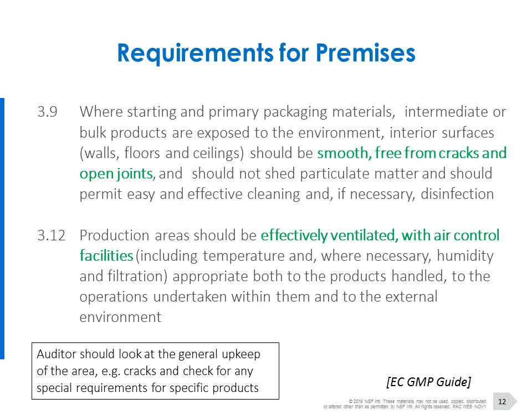So you will see, certainly where there is open product, most companies will not permit wooden pallets to be present in that area, and they typically use maybe cardboard or plastic pallets. But generally, if you're auditing the premises, you should look at the general upkeep of the area. Remember, there will typically be many forklift trucks operating in packaging areas, and it's very easy for them to damage the floor or the walls and create breaks in the paint, which can then go on to create actual particulates.